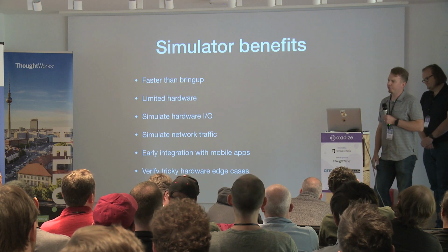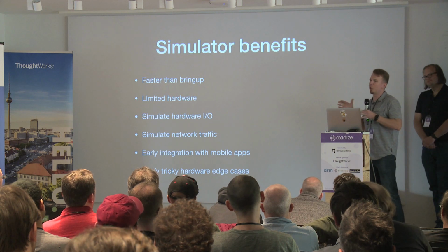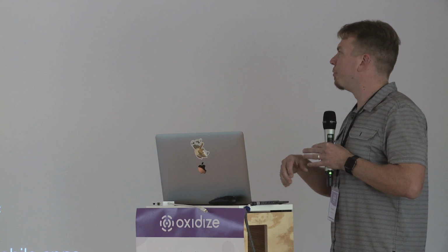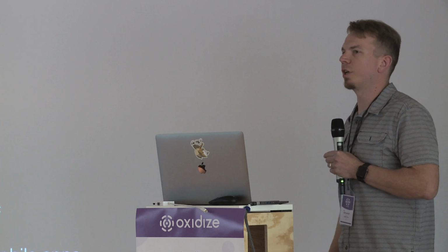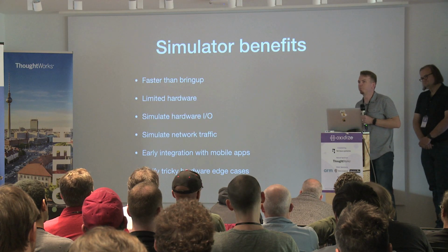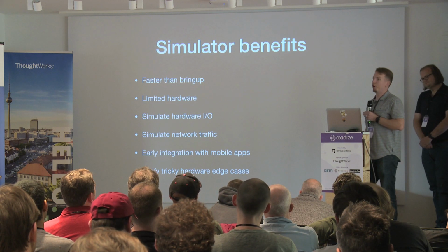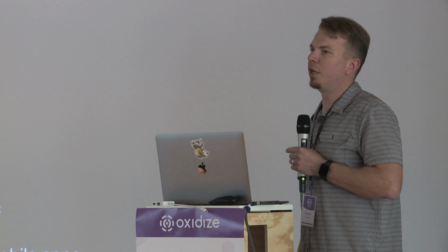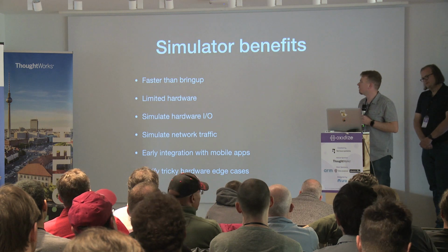Some of the benefits that we experienced building the simulator is that, once we had designed the different modules in the system, we were able to implement the simulator version of things faster than the board support bring up was finished. And so we were able to start building application logic and actually testing it and verifying it before the hardware was ready to use. Even once we had hardware and the bring up was all done, we had very few hardware units available, and so it made it a lot easier for many developers to work on things by not having to have hardware for all the work that was being done.